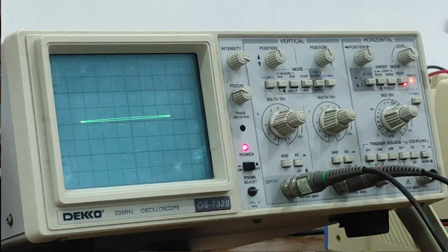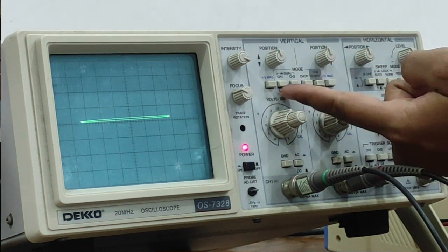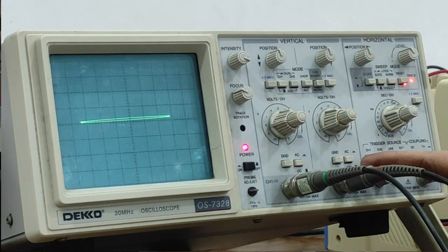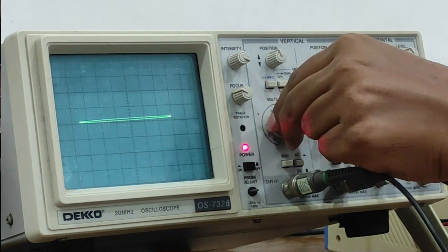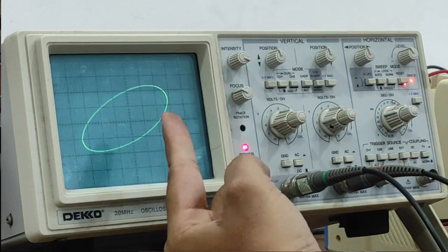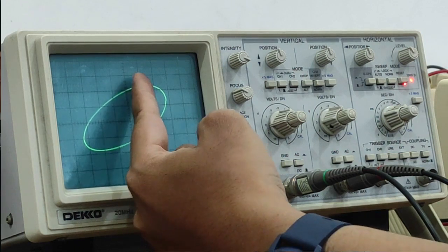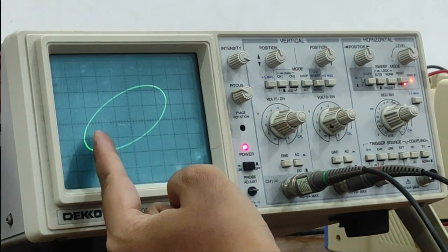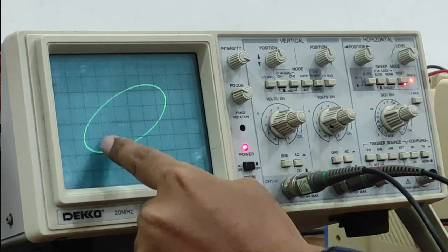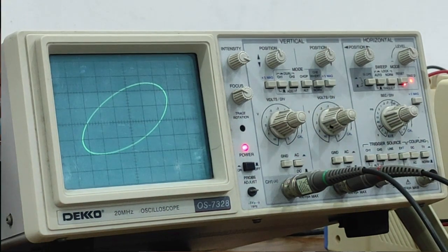After that, look into the oscilloscope display. In the oscilloscope display, you will get a figure like an oval shape, and then try to adjust the volt per div for probe 1 and probe 2, and also the time per div. Try to get a clear image for this pattern, and don't forget to measure the edges of this shape and then record them to your worksheet for this step.